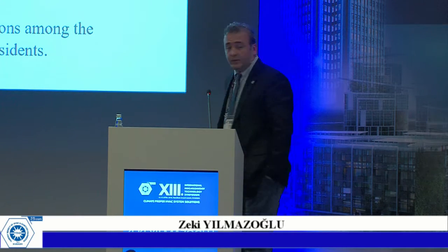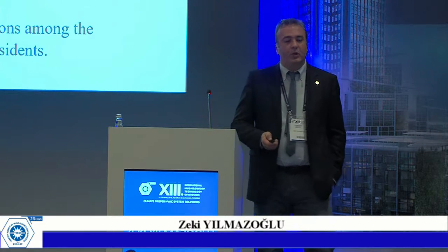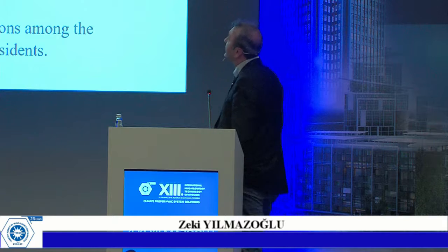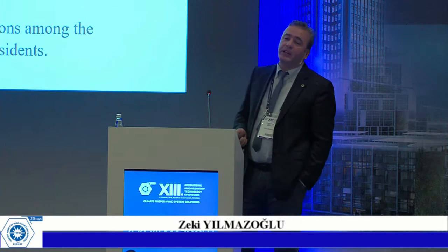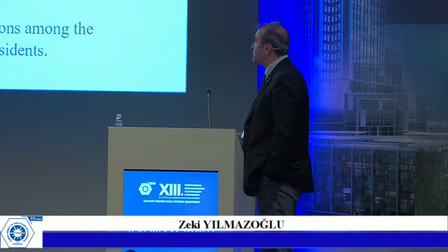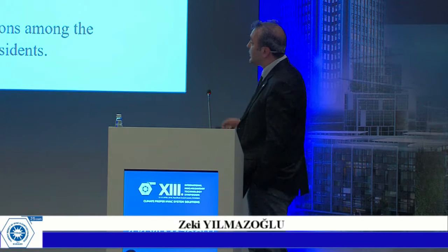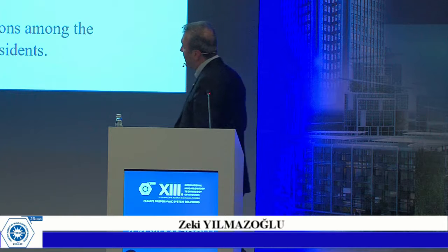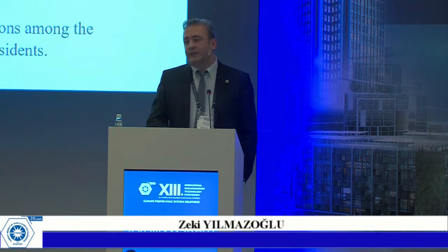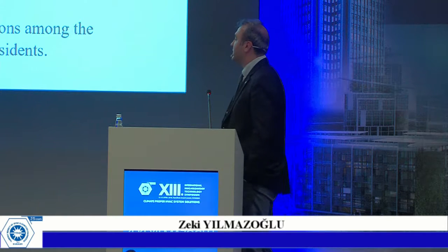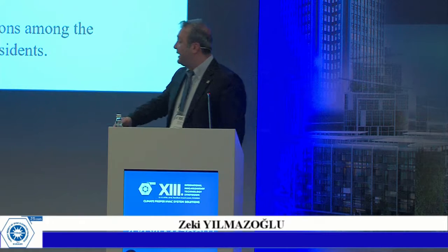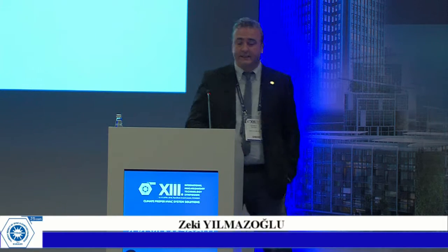Among all the factors determining the location of electricity production facilities in urban and regional planning is the wind direction. Prevailing wind direction has a great effect. The height of the stack is also of great importance. Emission sources close to tall buildings should also be addressed in terms of airflow and pressures. It's important, the pressures around the buildings. Inappropriate layouts may trap the emissions among the buildings and threaten the health of the residents.